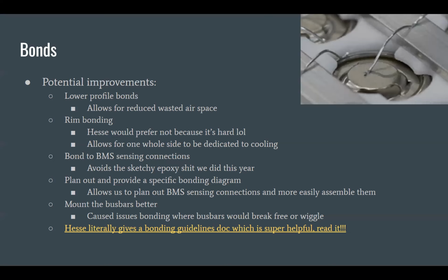Why would bonds fail? Bonds can fail for a number of reasons. Obviously, there's the fusing element: if you run so much current through it, it pops. Do you mean why it will fail to bond, or why it will break after it's bonded? Why would it fail to bond? Yes. Let's say you have a bus bar that was bent when we manufactured it, so it's actually formed. That means that when we epoxied it, chances are the center didn't actually epoxy and just the ends did.